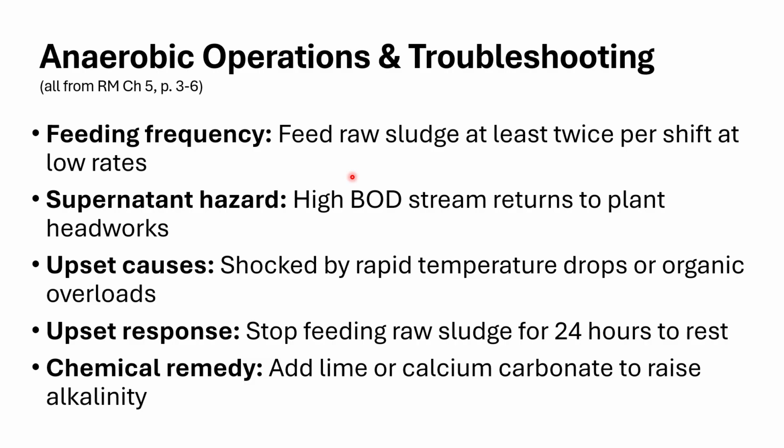You remember what we talked about? We basically said we don't want rapid changes to that sludge blanket, because if we have rapid changes to the sludge blanket, we run the risk of sending that sludge back into suspension. We don't want that. So think of sludge blanket management as a slow moving process so that we maintain the sludge blanket in the primary clarifier as well as the secondary clarifier. But we're also doing another thing with that. We are maintaining our feed rate for our digester, for our anaerobic digester. That's why we do this slowly. We're balancing things and we're moving things fairly slowly, but we're going to do this twice per shift.